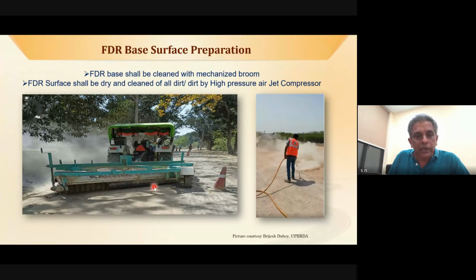Base preparation before laying the surfacing layers: the layer has got to be cleaned either by a mechanized broom, and all the irregularities and dust and everything needs to be cleared out by using an air compressor or by blowing air over it.